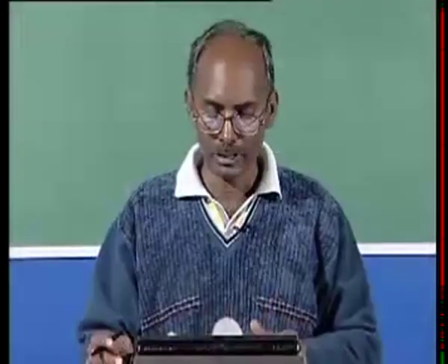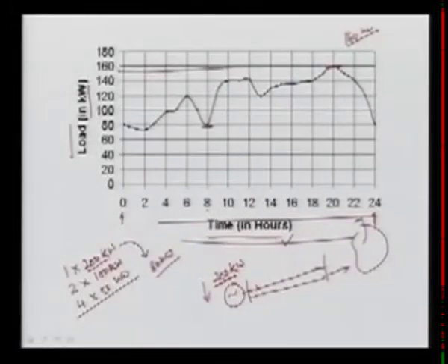You are running one unit continuously for all 24 hours. At one time it is maximum loaded, and the remaining time it is half or partially loaded. If a generator is partially loaded, the efficiency will not be better, since efficiency is best when it is loaded to full capacity. So the cost of electricity generation will be more.